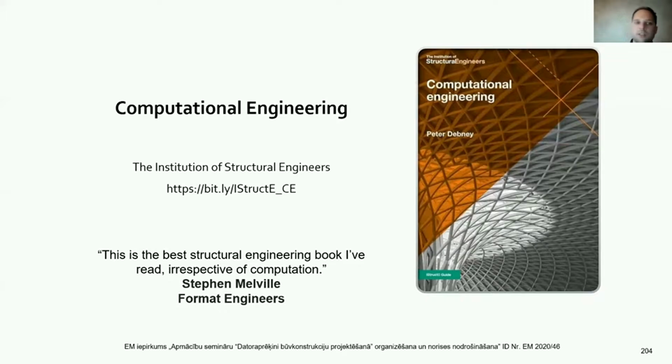Could you suggest some form finding software for cable structures? Yes. The software that I work on with Oasis is GSA. GSA has a form finding option where you can do force density and soap film and structural properties, normal properties form finding. That is very successful and is used a lot by engineers like Arup and Buro Happold and Expedition and so on.